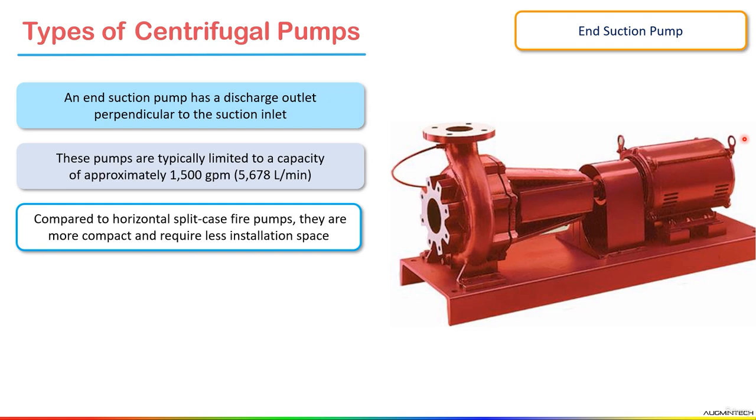If I compare this end suction pump to the horizontal split case fire pump, it is more compact and requires less installation space as compared to the horizontal split case pump. Remember, but if you compare this pump to an inline pump, this end suction pump requires more space.